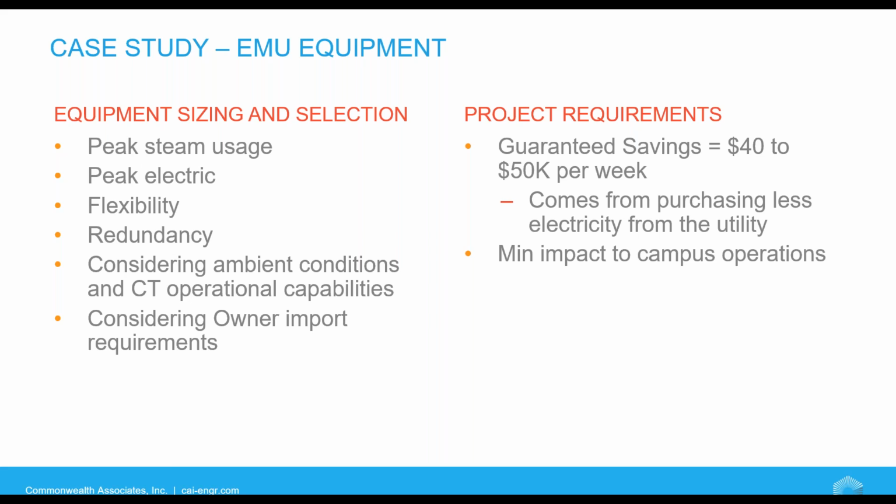Ideally, you pull the data from the past few years in hourly or daily increments to look for trends, because it isn't as simple as finding the maximum output and sizing everything to that. You need to keep down the need for potential turn down of equipment to ensure it meets your needs so that you can supply both the maximum and the lower levels. And if you're unable to do so, you may need to install multiple smaller units to increase the turn down range.